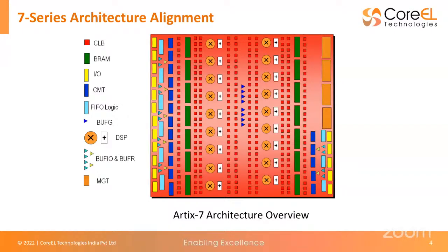As we can see, we not only have CLBs, but we have dedicated block RAMs and dedicated distributed RAMs. Depending on the architecture, we can also find UltraRAMs and high-speed memory units as well, right? Similarly, when we talk about FPGAs or VLSI in general, we'll be able to see dedicated resources for dedicated tasks.